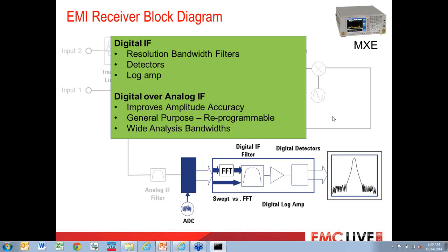However, I left out an important piece, and that is, what are the different scan types? How do we collect this frequency information? Historically, the step scan was used. The step scan is essentially the LO tuning to a frequency and then waiting there while we dwell and measure that frequency point, and then retuning to a new frequency. And we did that across the span.